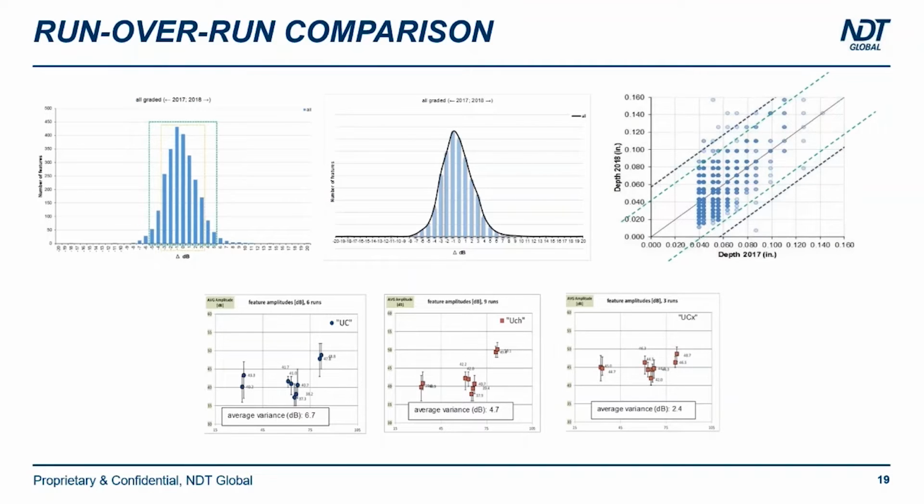So what else do we check on the data? All the other variables. When we're talking about ultrasonic robots, we're talking about amplitudes that are then being translated into depths. So it is paramount for us to understand how these amplitudes are behaving. This is pretty much the foundation of what we are going to report. All the ultrasonic tools, depending on their resolutions, will show significant variance. This variance has been proven and tested in the lab.